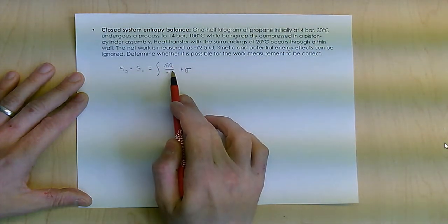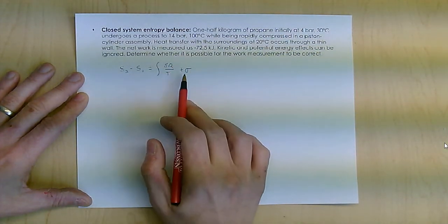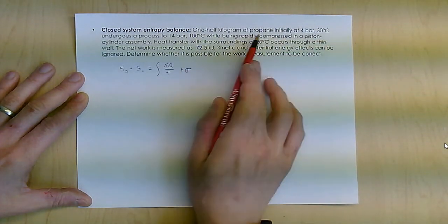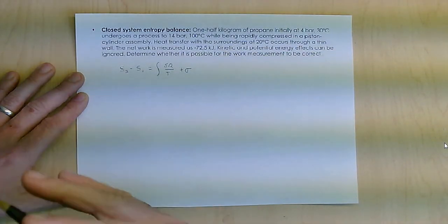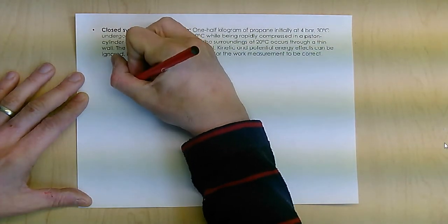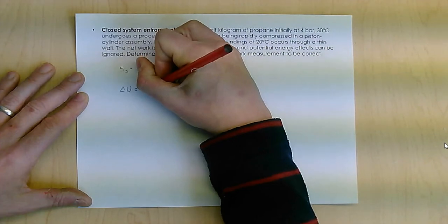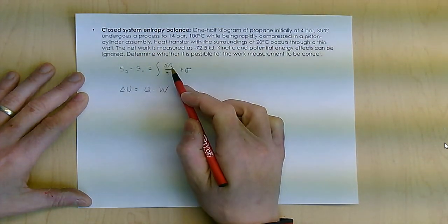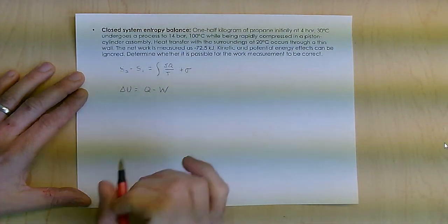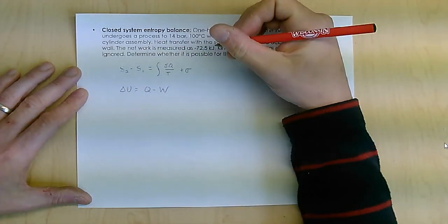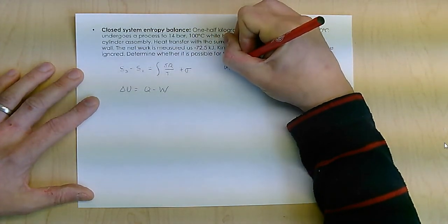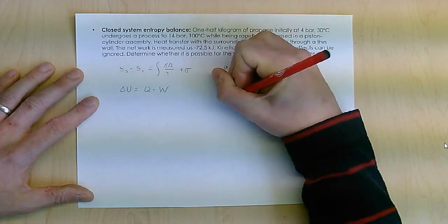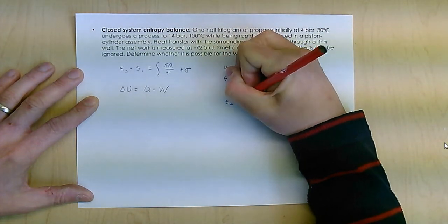I need to figure out the heat transfer so that I can apply it into this equation as well. I know the work. I also know two states. Therefore, I can use the first law equation, which is, again, delta U equals Q minus W. So I'll first start by finding Q. Then using Q, I can calculate sigma. Now, before I do that, let me figure out U1, S1, U2, and S2. Look up these states.